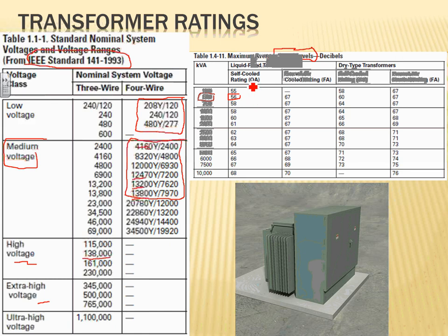There's self-cooled here, where there are no fans. Then there's forced air, that's when they put big fans and blow air at them. And then this is for liquid, of course, if you have a liquid-filled transformer. And if you have a dry type, which is most likely, the same thing applies, either self-cooled or fans. You can see if you have fans, it's going to be louder. So I thought I'd throw these things in so you're aware, if you have a transformer, especially in the medium voltage range, in an area that requires you to be quiet, that this information is available for you.